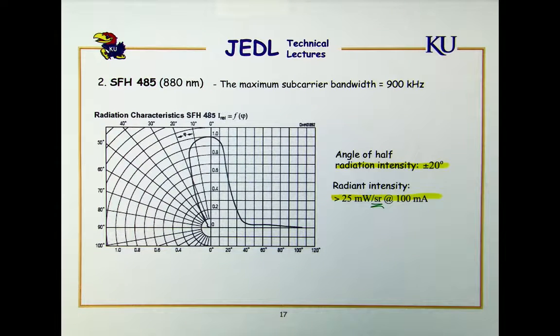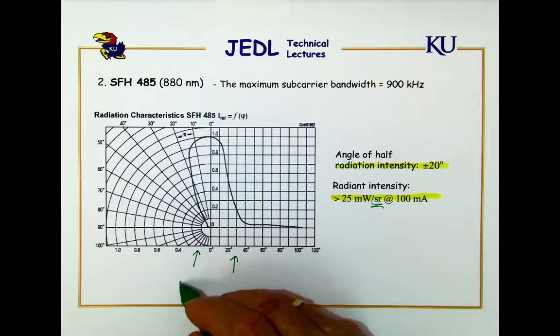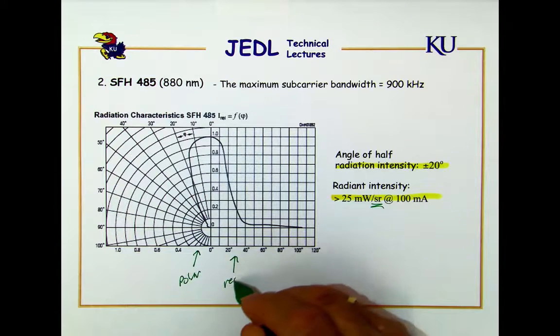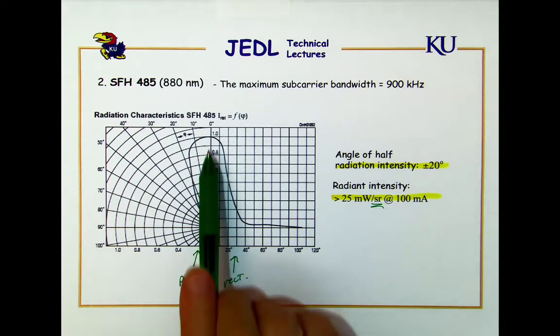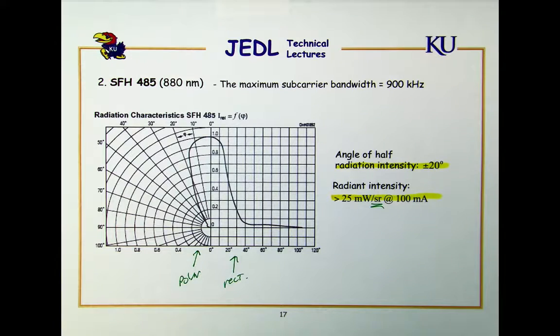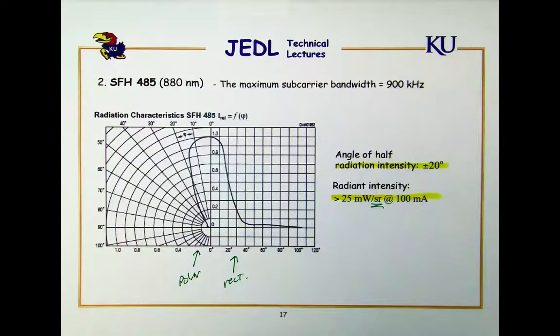Look at this chart. I didn't mention anything about this before on the other page, but there are really two representations here. One's polar, and the other's rectangular. They're saying the same thing, and they do it this way because everything that happens on the left happens on the right. The polar coordinate expression on the left gives you a feel for the nature of the radiation pattern, but the information is the same as on the right, where it's plotted out in rectangular coordinates.